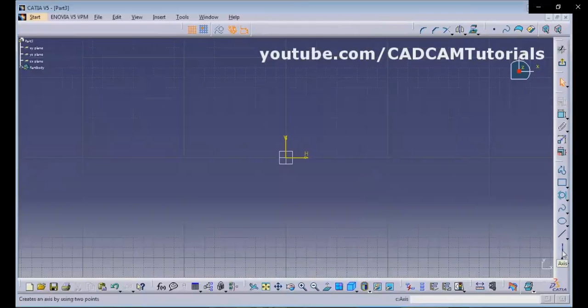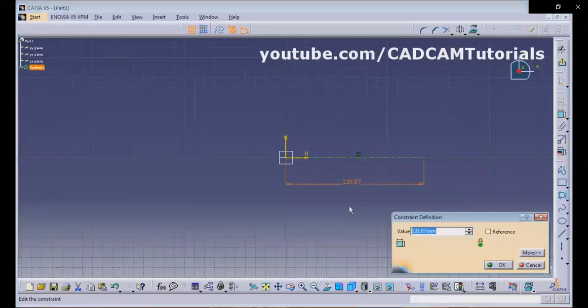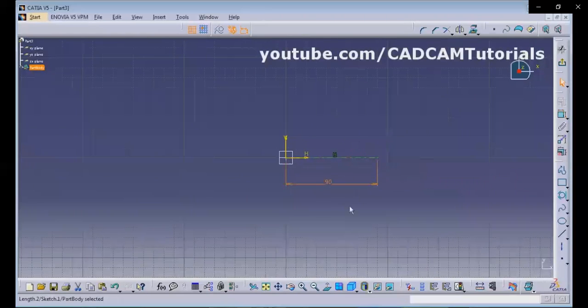So we will take this axis tool, take the first point, take the second point and give the dimension. Click on constraint, click on the axis, place the dimension, double click to edit. The dimension is 90.